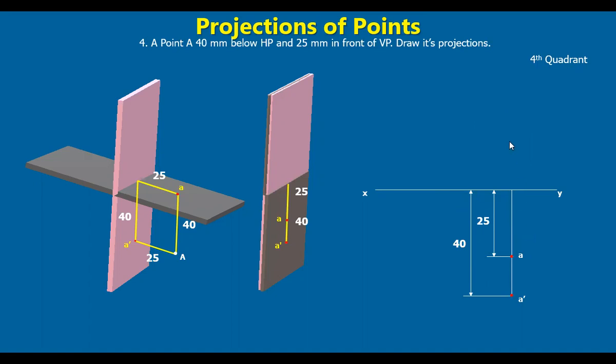And one more thing, we don't have any such second angle projections or fourth angle projections, because you are getting both the projections on one side. Suppose my object is a complicated object and I get a top view here, and the front view is also falling on this, it's very difficult to get the details. So there is no such second angle projection or fourth angle projection.